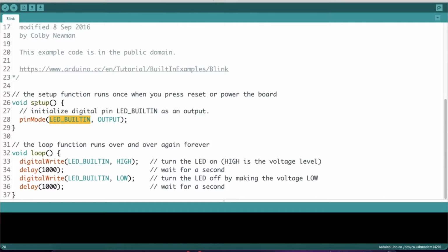If you have studied the structure of Arduino, then it has two things. One is setup, one is loop. In the setup mode, we initialize and set up the pins and whatever set of information does not change over time in the code. That type of data is set up in the setup section. For example, the pin number that the LED is connected to, pin 13, and that it is going to act as an output, is a setup thing. Let's say if you are going to add some sensors, then setting the pins to input is a setup thing. So whatever we set up on the board, we write in the setup section, and whatever functionality we require that particular thing to do is implemented in the loop section. That is how we can differentiate where things should be written.